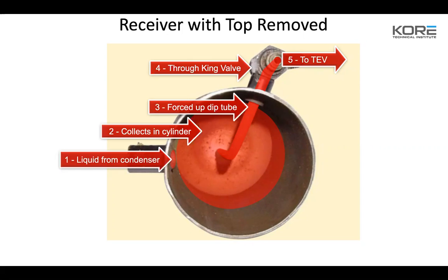I'm not anti-gauge up, but it's the very, very last thing I like to do, because anytime we introduce our hoses to the system, we have a potential of introducing contaminants into the system. So I do not like to gauge up to things unless it's last resort or I'm making the repair. If I need to gauge up to do some calibration, then I will. But mostly I want to be able to use my meters and my hands, and my senses.